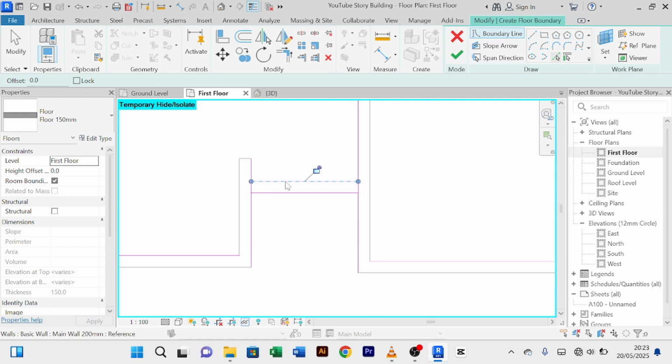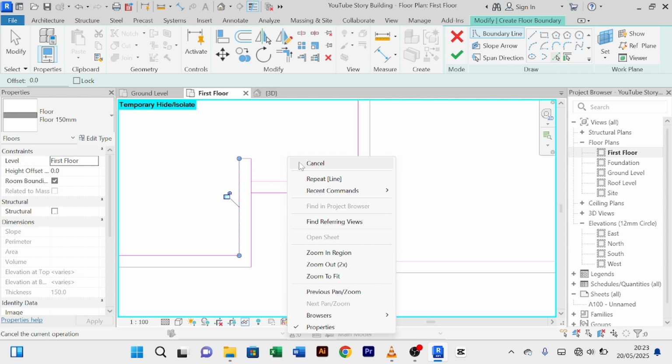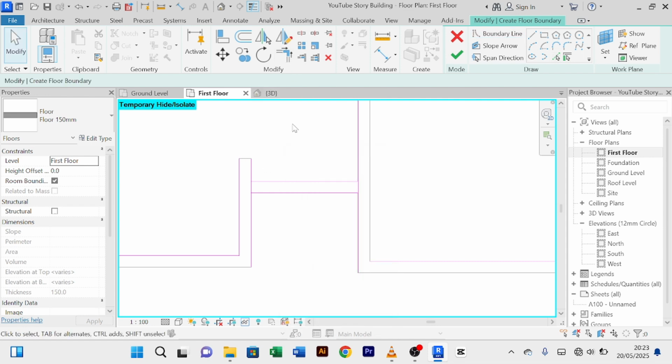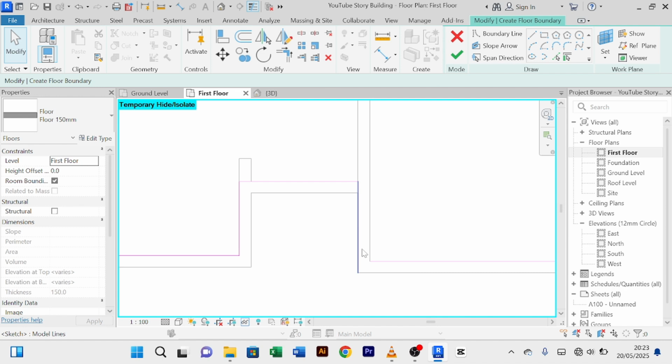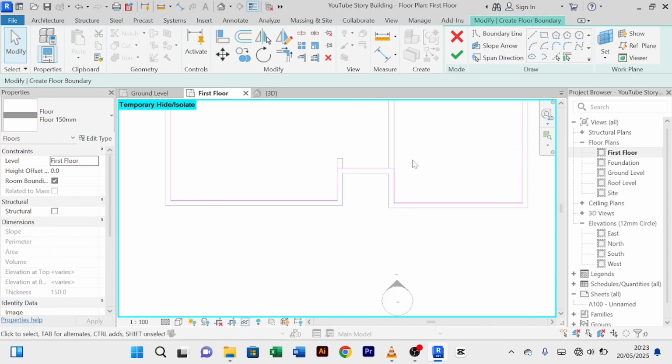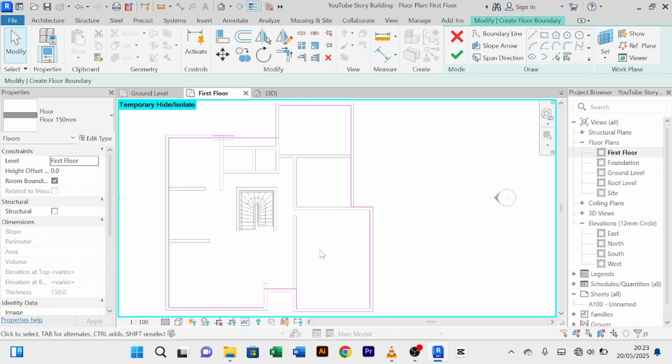But of course, you know, we're supposed to pick the interior sides as I had started earlier. So my bad, I'll connect that, connect this. I'll delete these ones outside. Even this I need to delete. Then I have to pick this one. Then I pick my trim to extend tool, and then I connect that. So we have drawn our floor for the first floor.